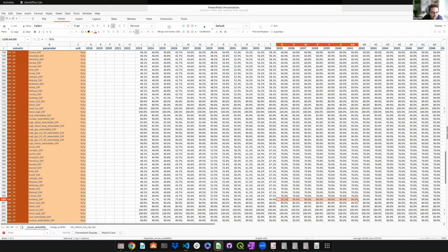But for the capacity expansion planning, especially once we go into 5-year steps, because you're not solving every year, you can get anomalies where if it's a year that Koeberg is on maintenance or not on maintenance, it can make a big change to the results. So that's why for the capacity expansion model, we just assume a flat profile on that.